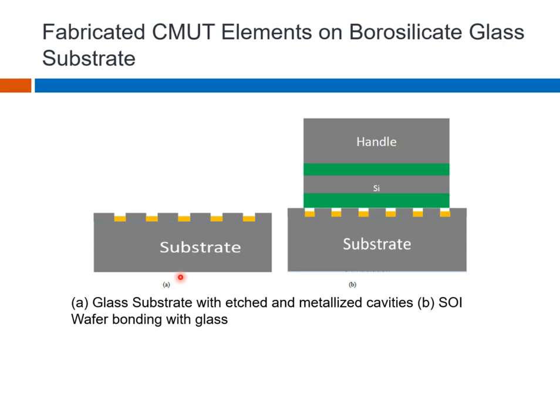This is a little bit about how we fabricated the CMUTs, since I showed the measurements. The fabrication was based on anodic vapor bonding technology. We have a glass substrate, which you can see has etched cavities. The etching was done using buffered oxide HF solutions, and the gap height of 10 micrometers was chemically etched. The patterning was done first by a chrome mask using a photolithography process,